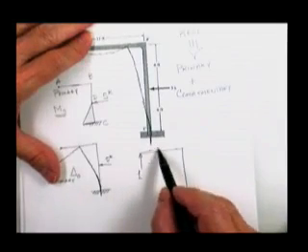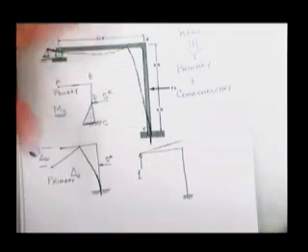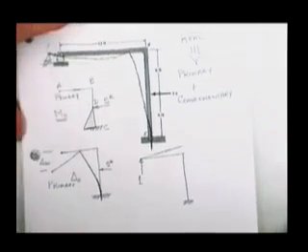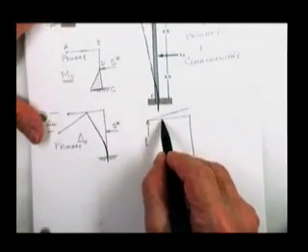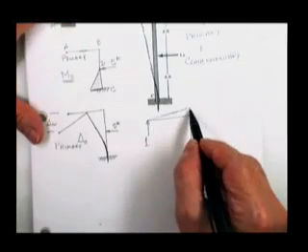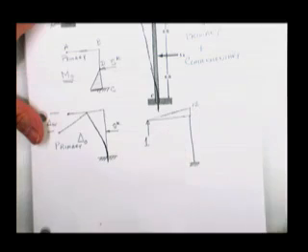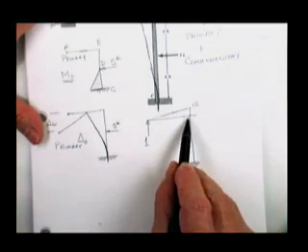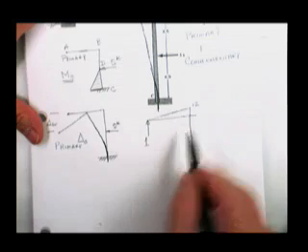This is drawn on the compression side. You should really, on simple things like this, be able to just practically sketch them. And this is 1 times 1, 1 times 2, 1 times 6, 1 times 8. This is 1 times 12. So this would be 12. And then as you cross the corner, whatever moment's on that side of a corner is the same as the moment on that side of a corner.